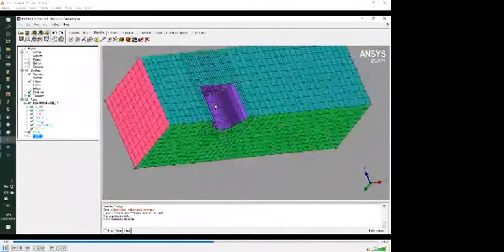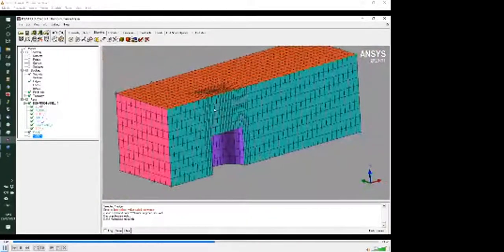Depending on the solver that you're going to be using, you could export this either as a structured IJK type of mesh or as an unstructured mesh, which is what most solvers can deal with effectively these days. In either event, you've got a lot of control over the mesh spacing, and you've got a lot of efficiency, and you can match your grid spacing very nicely to the topology of the object that we're meshing.